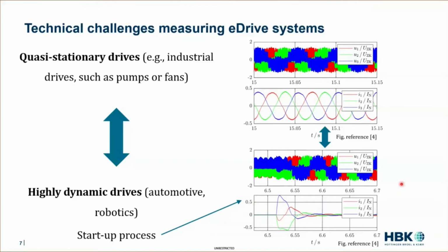And of course, you can do a zero crossing detection in order to detect or calculate an apparent fundamental cycle. But as we all know, a fundamental cycle is only defined for periodic signals. So of course, we can do evaluations as we do it for the steady-state operated drives, but it may also lead to some misinterpretations.